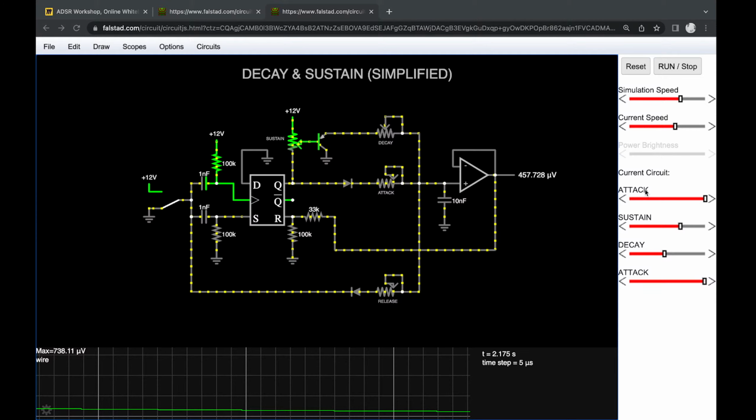Okay, and then AKA Nerd says, hello, isn't the reset pin triggered with a lower voltage than 6 volts? What's the logic? Yeah, so the way that the CMOS IC that I have, the 4013, behaves is that it registers half of the supply voltage as a high-level voltage. So in my case, I'm using 12 volts as a supply voltage, so 6 volts is the threshold when it registers a logic 1. This CMOS chip can work with more than 5 volts. It can actually work with 12, I think even with 18. I would have to check that again.